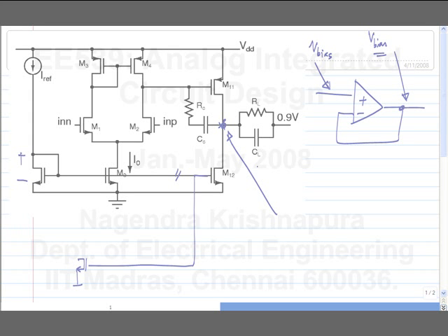That was the idea with the current mirror also. Now, the problem with this is, of course, now VGS is replicated, VDS is not. So I have to arrange this part of the circuit slightly differently. What do I do? What are all the different ways of biasing a transistor at a given current?